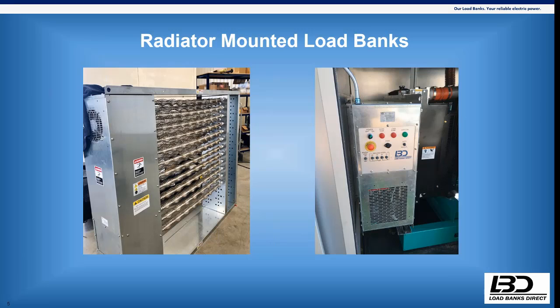So when I say it's an econoline solution, it really is. That 1,000 kW load bank that's outdoor stationary has its own pad. You've got to run conduit to it. You've got a cable up to it. You have to have a separate breaker for it. It's not just an $18,000 load bank. It's got installed costs associated with it as well.